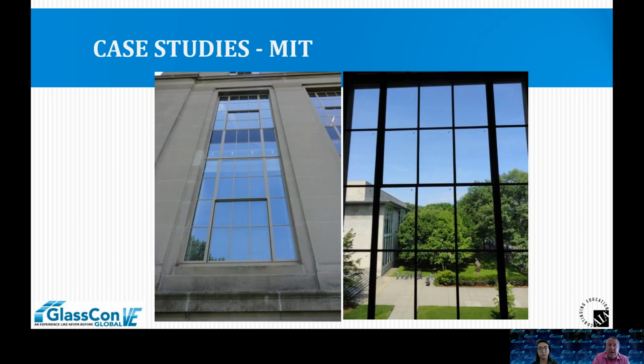Aesthetically, from the outside, and this is one of the most important things with these historic buildings, you don't notice a difference from the exterior. You don't see the caps, the buttons, or the little spacer arrays. The one thing you will notice is that when you go from monolithic glass to double glazed, you don't have 2 surfaces of reflection, you have 4. So your reflectivity bumps up no matter what you do. But beyond that, it pretty much looks like regular clear glass.